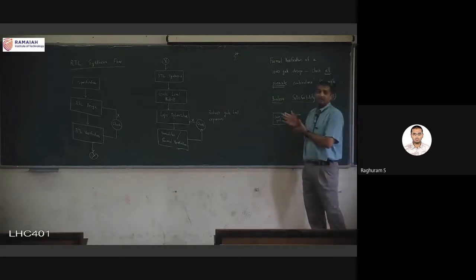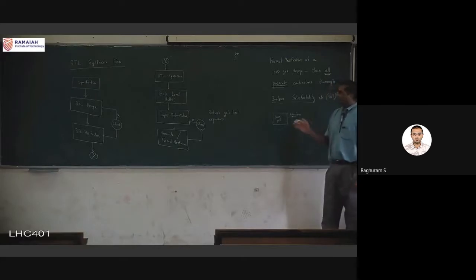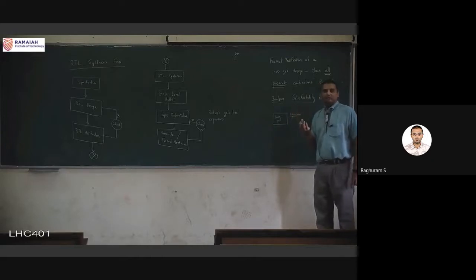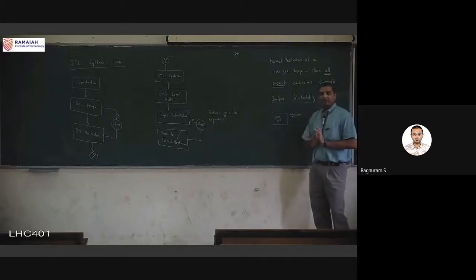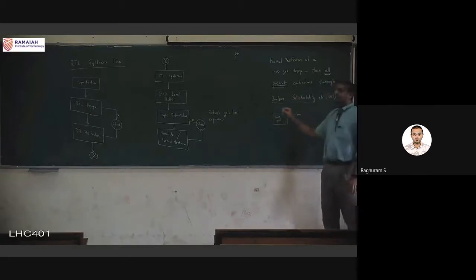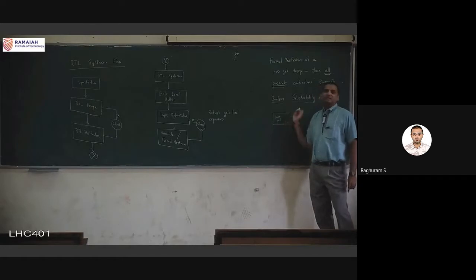We can ask questions like this to the solver, and this only works with Boolean because the 1000 gates' inputs and outputs can have only two values. So if you have 25 gates, for example, you can sit for maybe 1 week and work out all the possible combinations. That would be simulation. Formal verification uses completely different algorithms, mainly something called Boolean satisfiability. Based on these algorithms, without doing a simulation, it can verify statements like these for us.